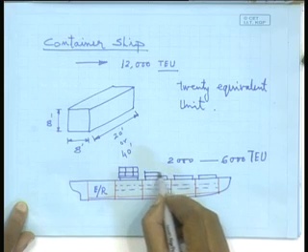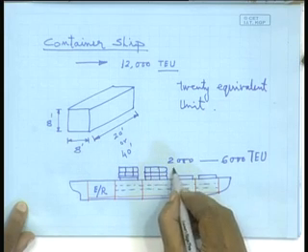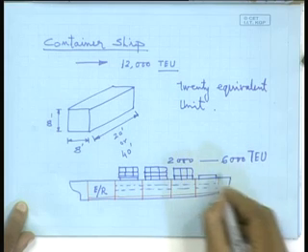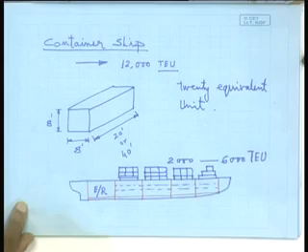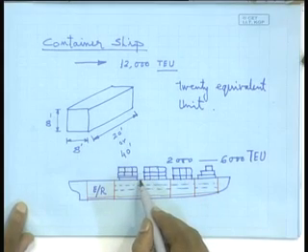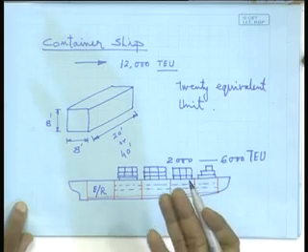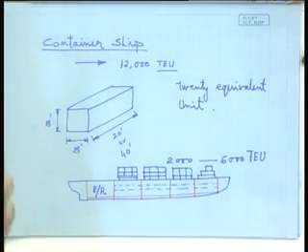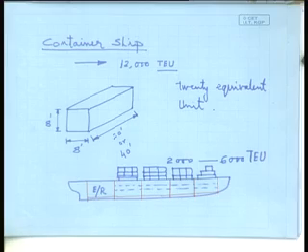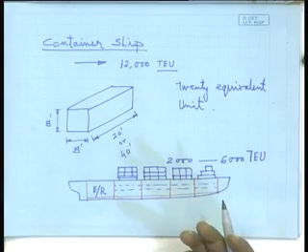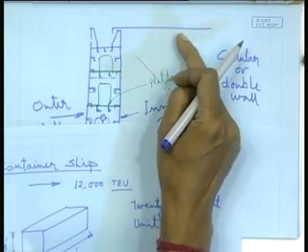that you may have an additional superstructure in the forward. These are my containers stacked on the hatch covers outside the hold. You have the required number in the hold, and you have provision for keeping, as I have drawn, 3 more tiers of containers above the hatch cover. Accordingly, the hatch cover has to be designed, obviously. That means it should be able to take that load, right.